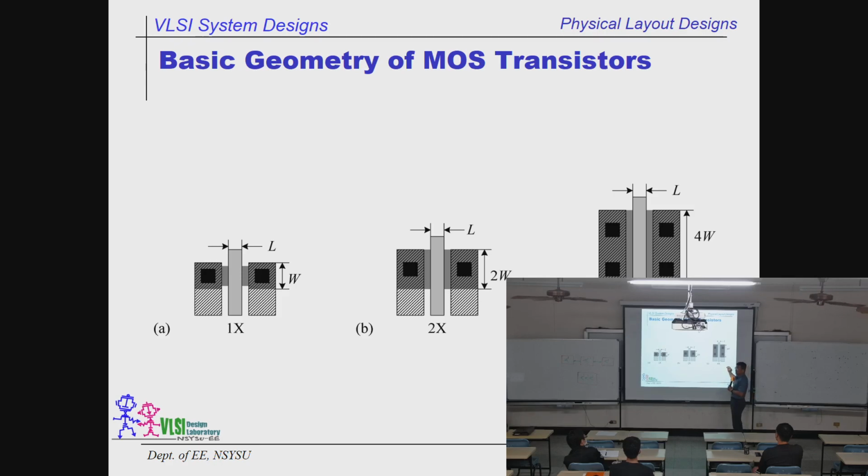So the only way you can do is increase the number of contacts. Use as many as you can. Because the more contacts you use, the less resistance you will create. That will give you a faster speed, a smooth transition of the signal. It will be better, all right? So mark down my words: use as many contacts as possible.